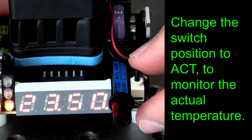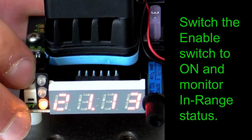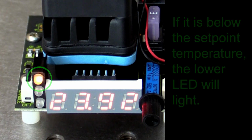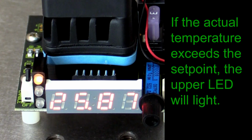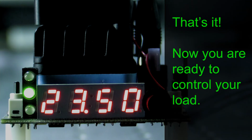Change the switch position to ACT to monitor the actual temperature. Switch the enable switch to on and monitor in-range status. If the actual temperature is below the set point temperature, the lower LED on the in-range indicator will light. If it exceeds the set point, the upper LED will light. The green LED is lit when the actual temperature is within 0.05 degrees C of the set point. That's it. Now you are ready to control your load.